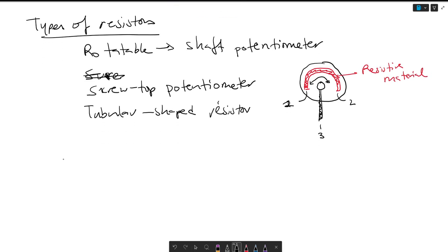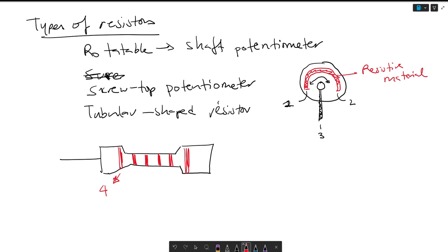And how this looks is a tubular. So this is a tubular shaped resistor, and essentially it's split into a couple of lines, specifically 6 lines, 1, 2, 3, 4, 5, 6, where depending on a table, you can look this up on a resistive table, these have values. And this is the amount that you multiply, the 10th position. So for example, if it's K, you multiply this value by 10 to the 3rd.